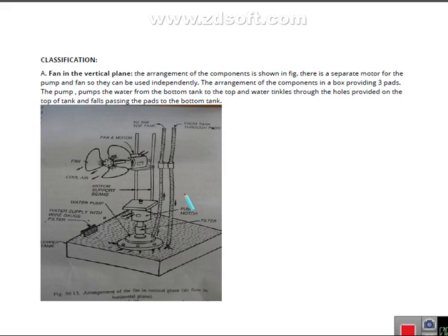Now this works on the basis of our comfort level. As you can see, it is the basic structure of a desert cooler in which a water pump is kept in a water tank. Around this section, a few pipes take the water from the bottom to the sides. These sides are provided with filters, mostly 3 filters on the sides. The water is allowed to fall on those filters, and we can compare the fan to an exhaust from the back side.